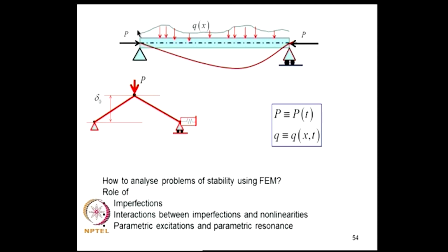In absence of axial loads P, we have studied how the structure vibrates, how it displaces, and so on and so forth. Now, the question we wish to consider is what would be the influence of simultaneous presence of transverse loads and axial loads like P. We will be showing that there exist certain critical values of P for which a slightest transverse load will produce huge responses in the system. So, the equilibrium state in the neighborhood of P being close to those critical values is unstable, in the sense a small perturbation will produce large responses.